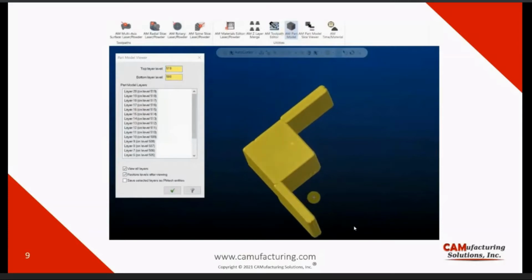And this basically gives the user the ability to have more stock for machining. So if a user wants to only have extra stock on these thin wall extensions, this is one way to go about it. As opposed to if the user is satisfied with just the additive finish, then they would have just equated the bead width to the spot size, and they would have just a single deposition instead of two. So this is our first case study.